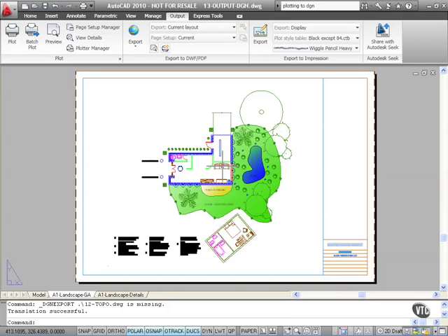So what I could do there is change the settings there again and go back and make sure that 12 topo drawing is there. The topo was the XREF drawing from previous exercises. It's not a major concern in this case, but obviously if we were working on a project, you would want to make sure that that topo drawing was also included in the DGN output.